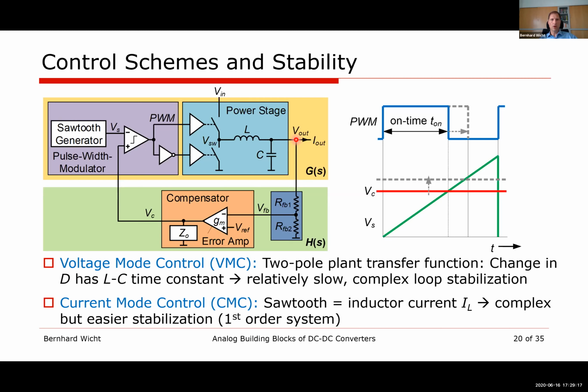Once the voltage drops below a certain tolerance level, it activates the whole circuit, sends a few energy pulses into the system, and then goes to sleep again. That allows to achieve very low power consumption. The overall power consumption in low power mode can be in the 100 nanoamps range, a few hundred nanoamps. That's something some ultra low power products can show already.